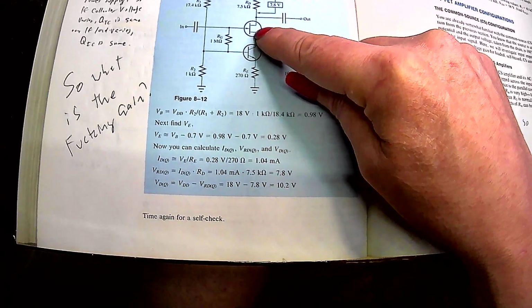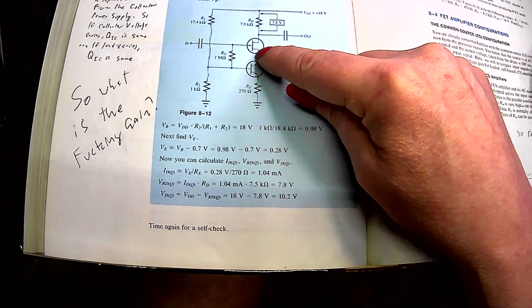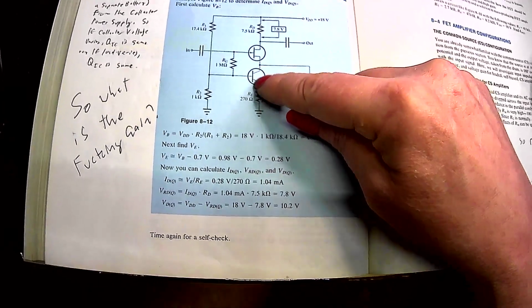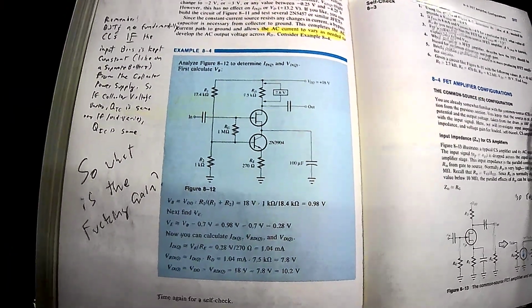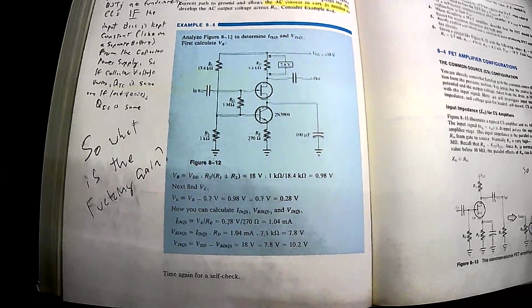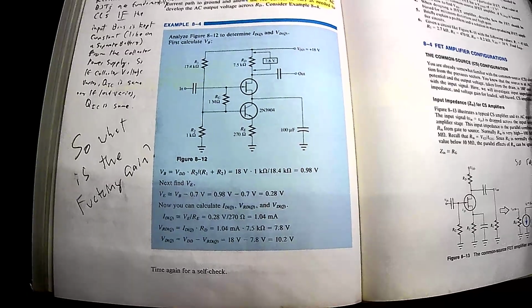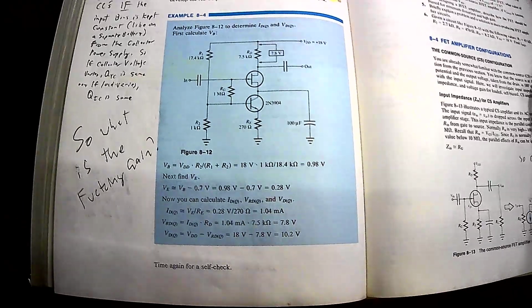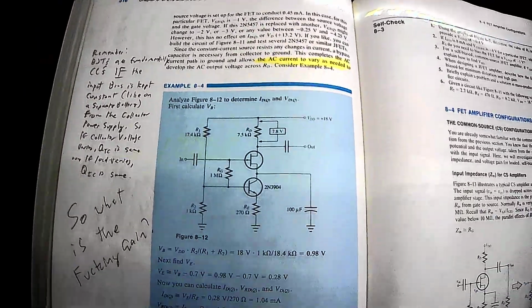I assume you've got to limit the current source to less than, obviously, the JFET's IDSS. But supposedly, this can reduce a lot of the uncertainty factors with JFETs, except that it's still not going to do anything about what your transconductance is on the input. And like I said, that alone is a huge spread. But at least this does minimize some of the ambiguity by having a circuit similar to this. And I may build this at some point to test it out, but not right now.